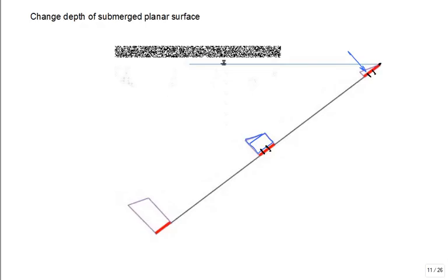So guess what? If I take a half and then I take a 1/3, guess where the resultant force is? Very close to the half. It starts to shift the location of y sub p, the center of pressure, and it gets closer to the center of the area, the centroid. True? We consider that negligible, I guess.